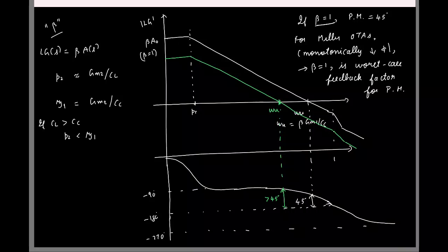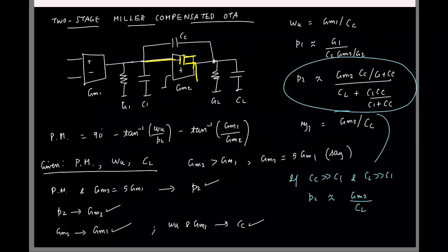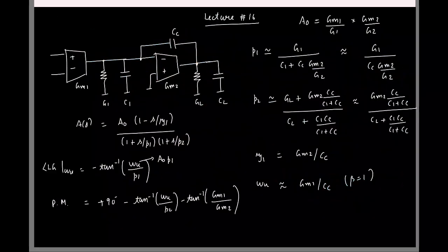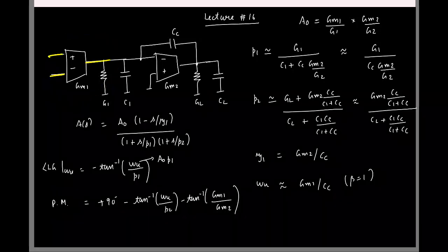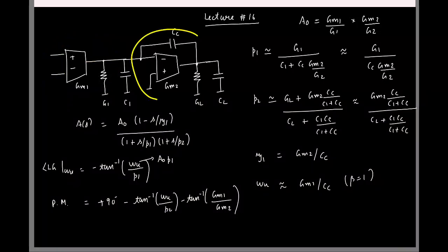Okay, so we have looked at this stuff at block level for some time, so let's go ahead and see the transistor level implementation. To refresh your memory, the first stage here takes in a differential input and provides a single-ended output. So what can I use for the first stage? The diff amp we saw, the 5 transistor amp, and for the second stage, a common source. Okay, so let's make that.